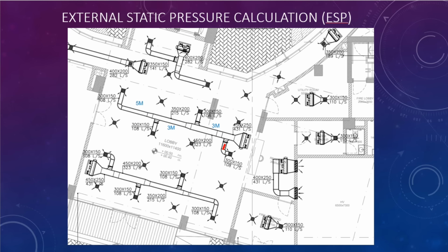And these are the branches which are touching the wall of the main duct, but they are not obstructing the flow. For example, if you have one volume control damper here, which is in the path of the air flow, air stream, that is the reason we have to consider whatever is there in the path of the duct, not in the branch. This SU piece, we don't. That's the reason we didn't consider the SU piece.